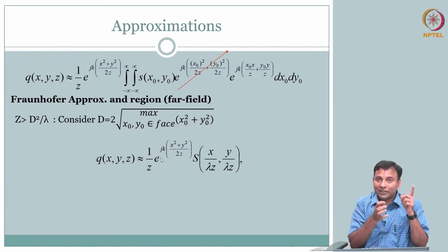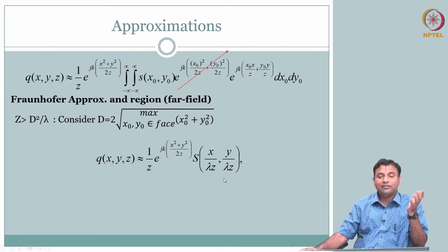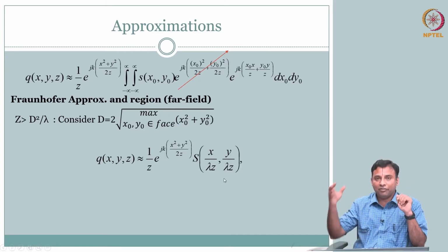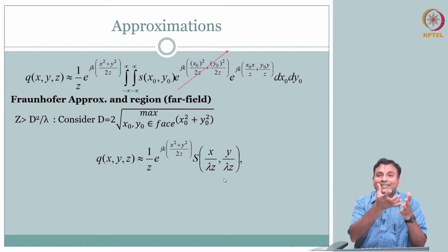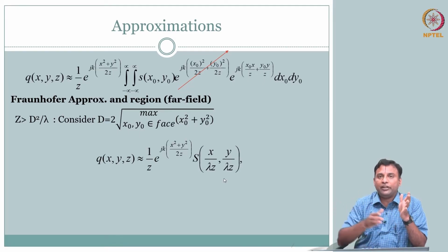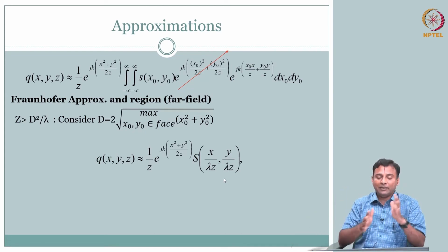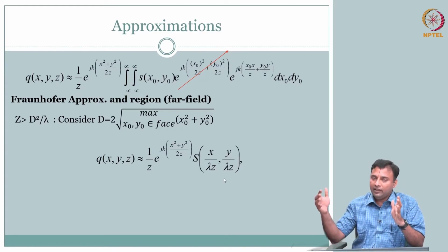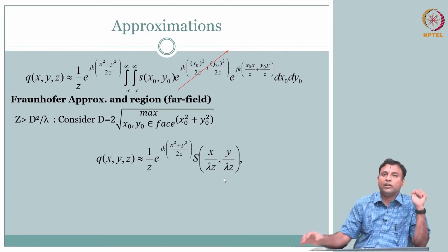The Fourier transform of the shape is going to give you the far field pattern, right? The pressure distribution in the far field, the shape of that. That pattern is mathematically described as the Fourier transform of this shape, and the size of this is also going to determine where this is applicable, whether you are in the near field or far field. So you see the size and shape of the transducer determines how this pressure is going out and where all you are getting the reflections from and the sum total that you are getting.